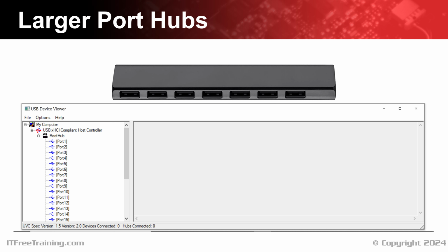I will next have a look at what occurs when you have a USB hub that has more than 4 ports. For a USB hub to be compatible with the USB 2 standard, it needs to have a maximum of 4 ports, so each port can be provided with a minimum of 100 mA. You can get non-compliant USB hubs that have more ports, running the risk that if you unplug devices, the bus may have too much power running through it, which could result in damaging devices. In this case, the USB hub is compliant with the standard.